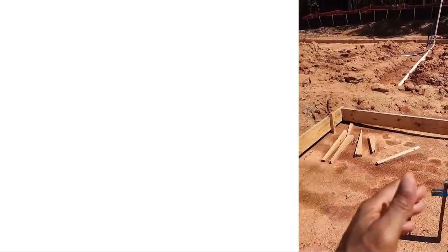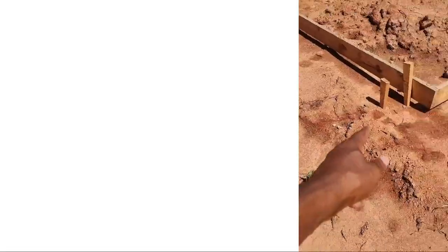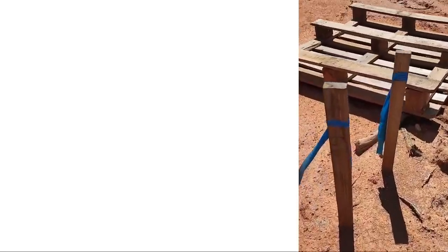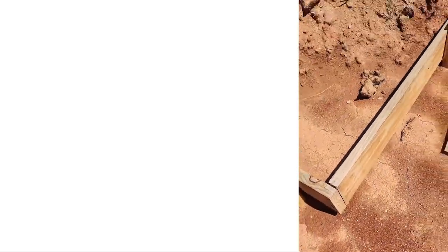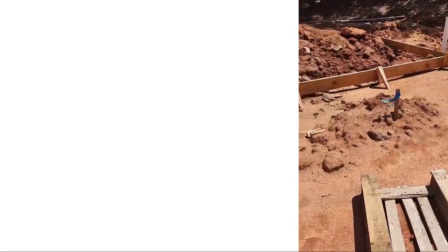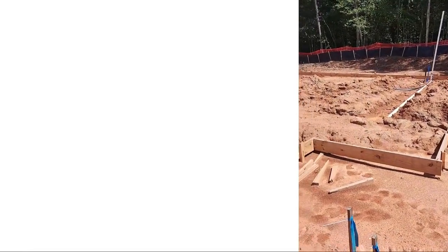So obviously we've moved it from here. What they'll do is they'll have a stake right here. Okay, and then they have a 5-foot offset right here and right here. So what you do is we pull from this 5 feet, and then we pull from this. You see it says 5 on it? We pull 5 feet, and it brings us to this corner. Likewise here, we pull 5 feet, we go that way, we pull 5 feet, we come that way, we get that corner. That was staked all around the property. And this is what they did.